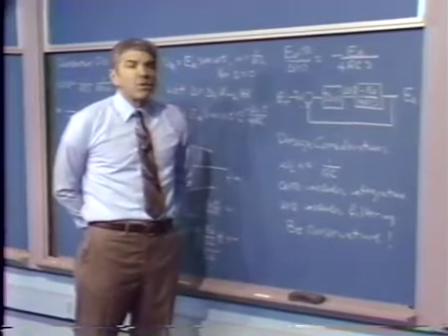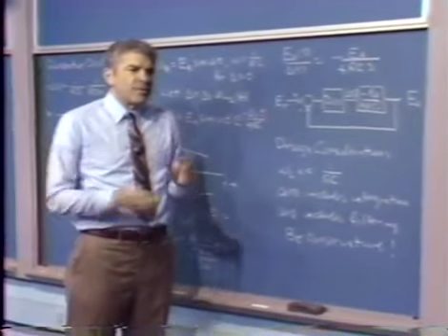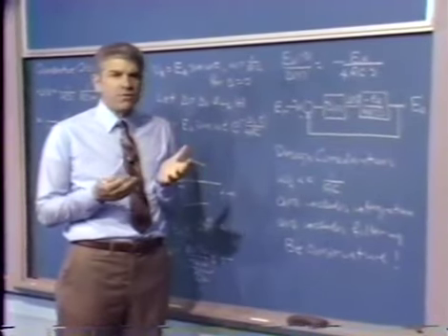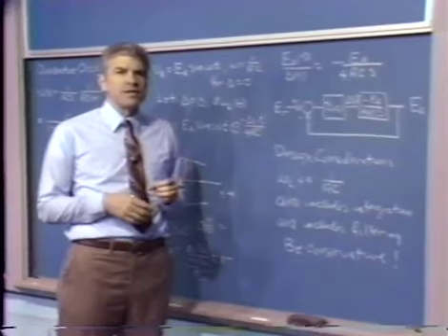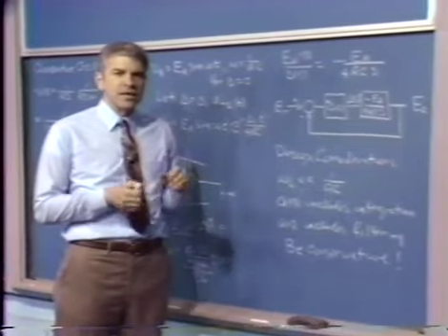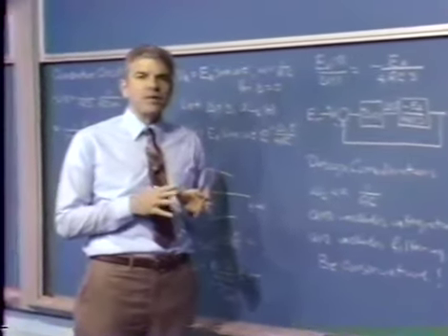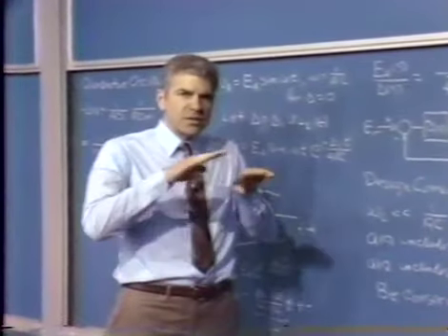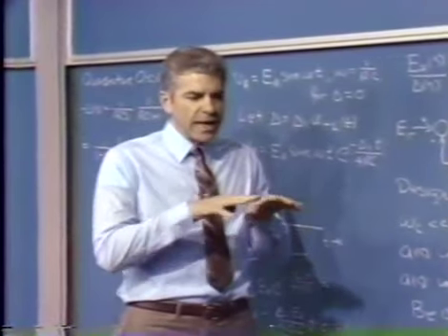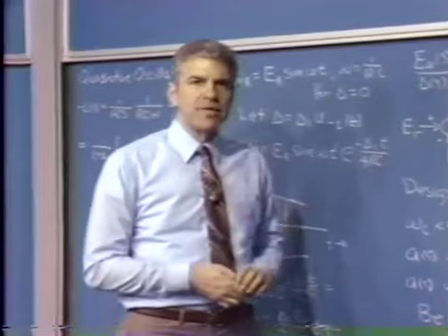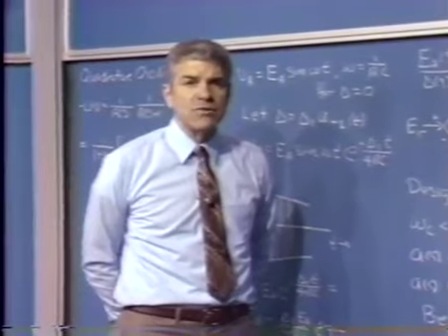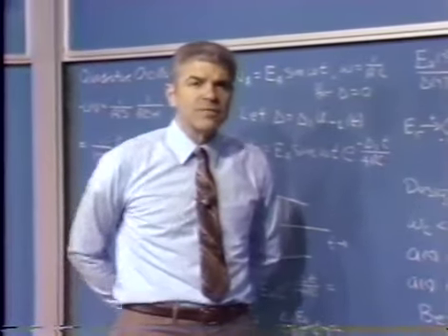Finally, we need some filtering. If we think about the way we'll do this, we can't get a perfect detection of envelope. What we might do, for example, is a full wave rectifier. That's one possibility. Actually, the actual circuit that we'll look at is a little bit more sophisticated than that. It does some phase shifting and then a rather neat multi-phase envelope detector that gets us fairly small ripple. It's equivalent to using several different phases and just getting a scalloped kind of an output waveform. But there is still some harmonic content, some high frequency noise associated with that measure of the envelope.